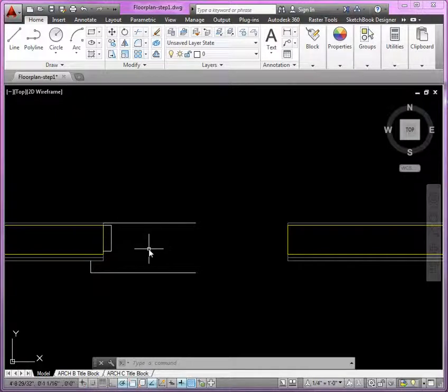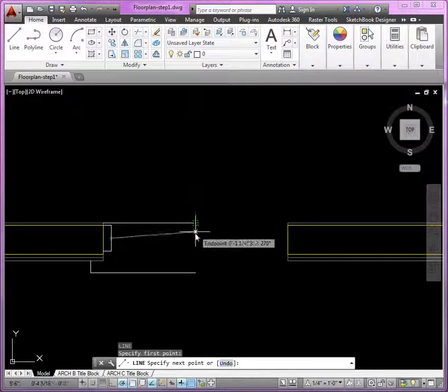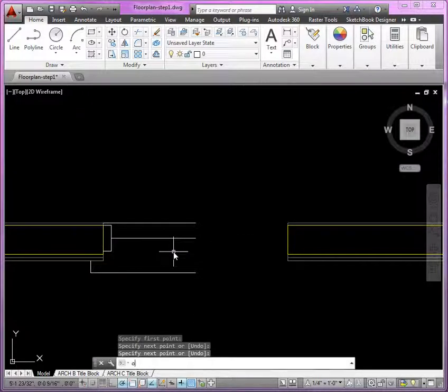Here's one half of the frame, and we're also needing to show the glazing, right? So here, the glazing there, we could start at the midpoint, line it up with the middle there, offset just 1/2 inch, I believe.